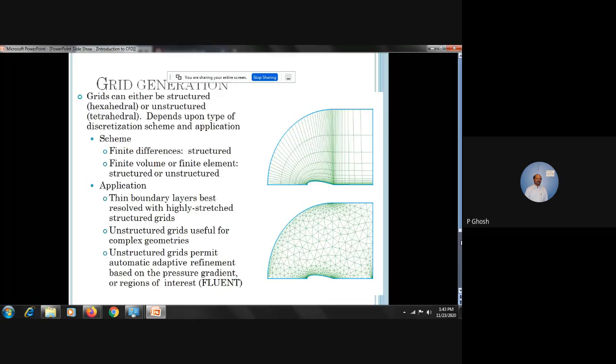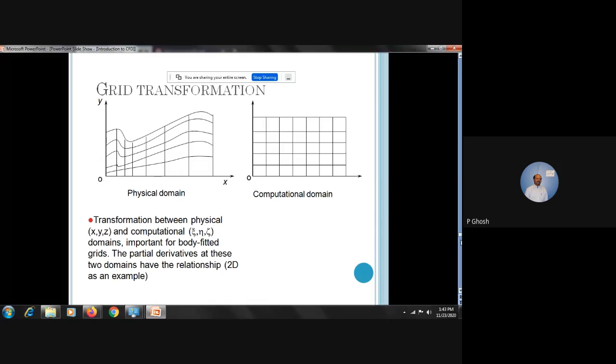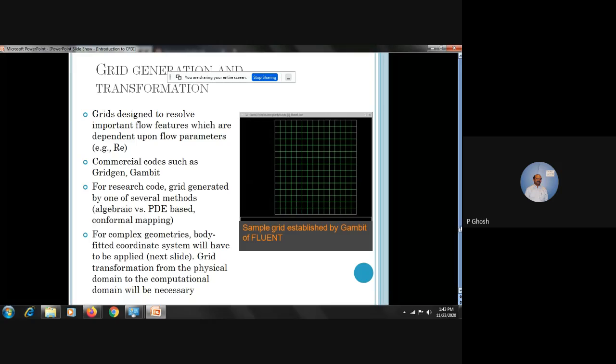So the number of grids you have enhanced. Don't give a large number of grids at the first point. You first do 10 by 10, 100 by 100, and then 200 by 200, and then give the millions of grids. Because you may have some problems in the model or boundary condition implementation, don't take the risk. It will hang, or if you have sufficient computational power, it will run for 7-10 days, and you are not going to get any significant result out of it.